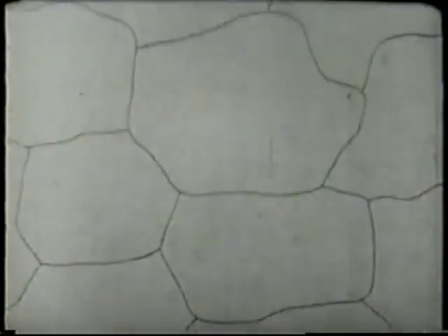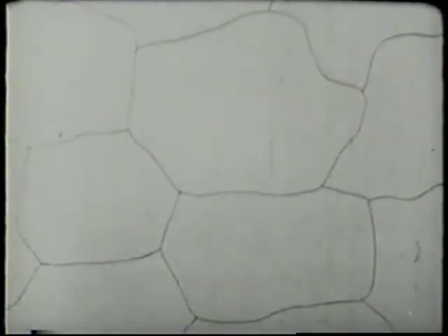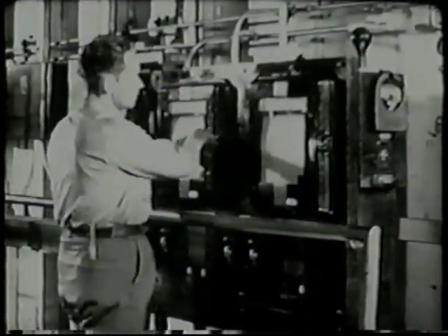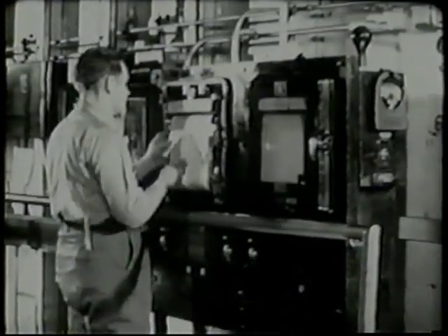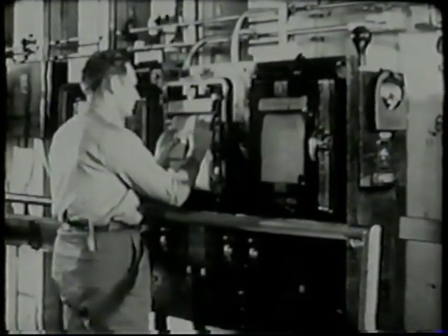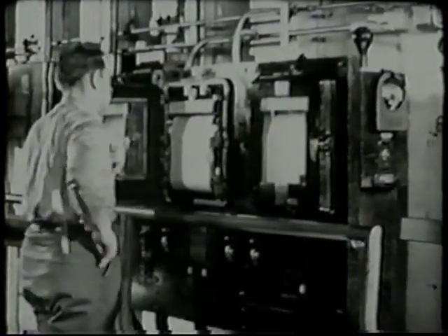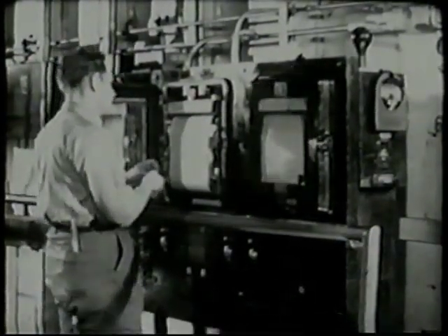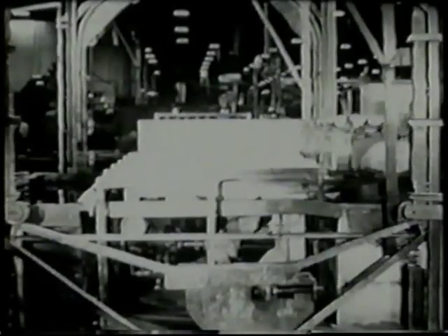The load of alloy parts is quenched by the cold spray for a period of several minutes. The water accumulates at the bottom of the booth and is carried away through drainage pits to be used over again in quenching. The microstructure of the metal now shows most of the copper dissolved in the aluminum. The quick quench captures or holds the solid solution in this condition. After a load is removed from the furnace, an inspector checks the pyrometric control record to make sure that the load has been within heat treating temperature limits throughout the soaking period.